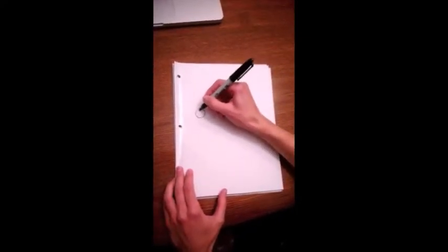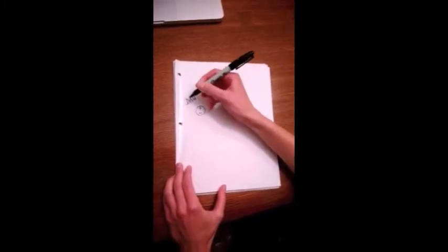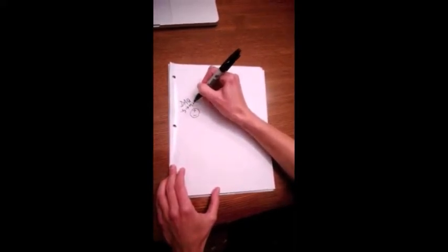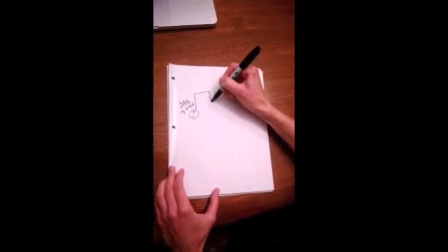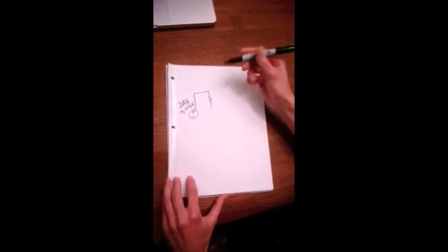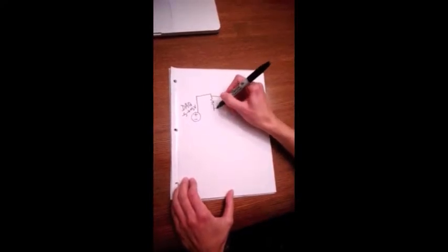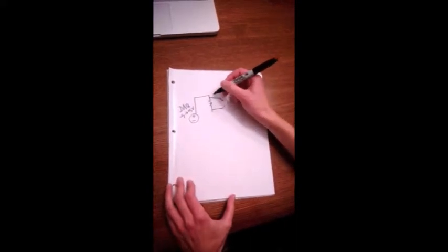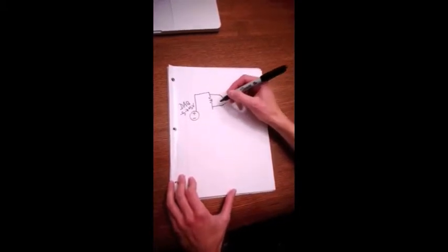Our setup for the circuit is we have a power supply, which is our DAC, and our DAC voltage is between -5 to +5 volts, and then we wire that to our shunt resistor, which is 1k ohms. And then, because this is a known voltage, we can measure our voltage across the resistor and get the current for our circuit across the first resistor.